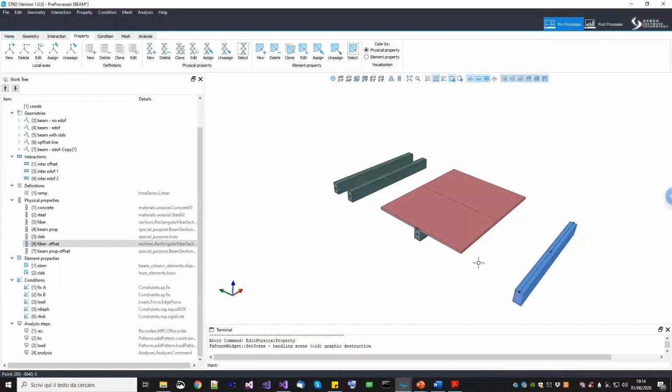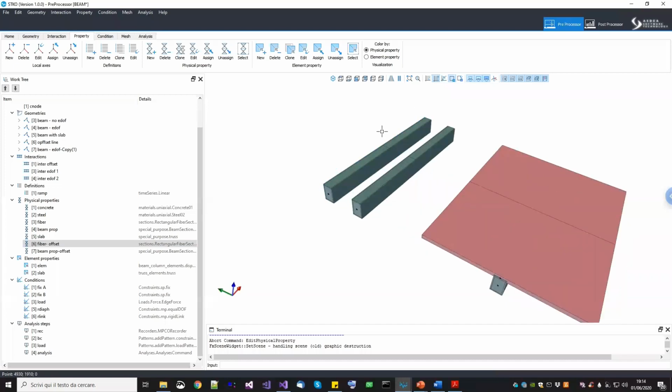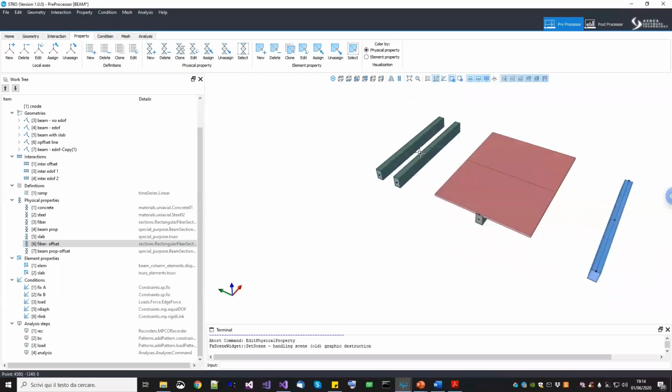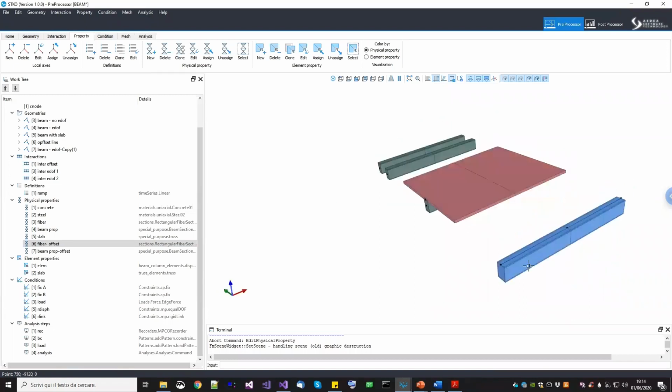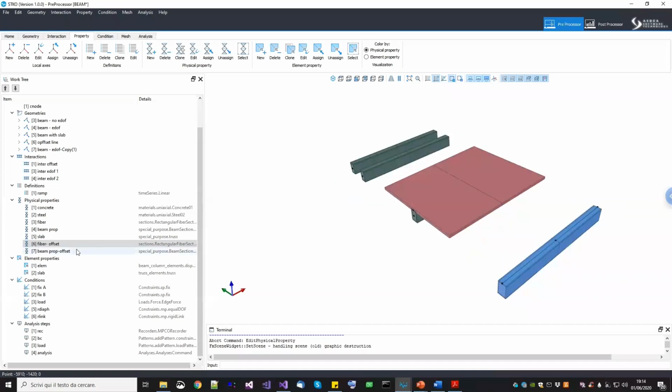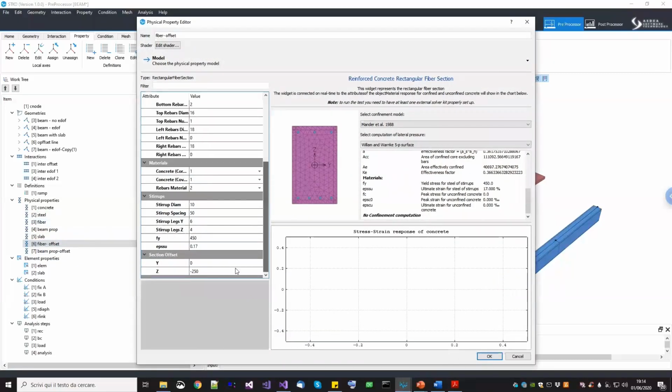Probably if you have followed one of our previous tutorials, we have seen that the problem of high normal stresses generated by this example can be solved by using an axial release, okay? Now, in this example, I will show you a different approach, which is even more similar to the real solution, which is using the section offset, okay? Before, I couldn't do it because we didn't have the tool in STKO to apply the section offset. Now, in this new version, you have it, okay? So every section, either the elastic or the fiber cross-section, has these offset fields, okay? Both in Z and Y.